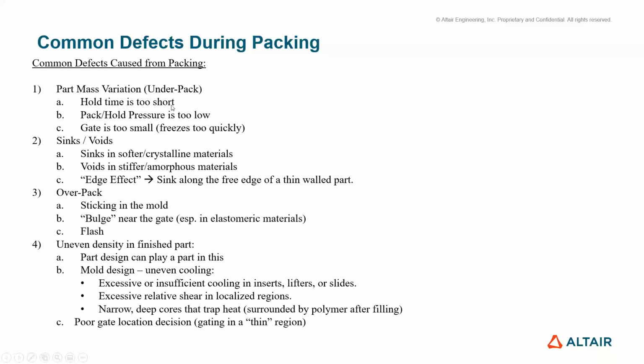If you freeze a gate too quickly and you don't have enough pressure in there, you're also going to have issues with packing. And you'll see a difference. I have some pictures in here. You'll see the differences. Sinks and voids, same basic effect. They're caused by the same principal physics. One's a sink, the other's a void. Why? Because voids occur in stiffer materials, generally amorphous materials like polycarbonate, where the skin freezes and then the inside is hot, and as it shrinks to the point where it cannot cause the sink at the surface, it breaks away from itself in the center. It looks like a bubble, and there's no air in that bubble.